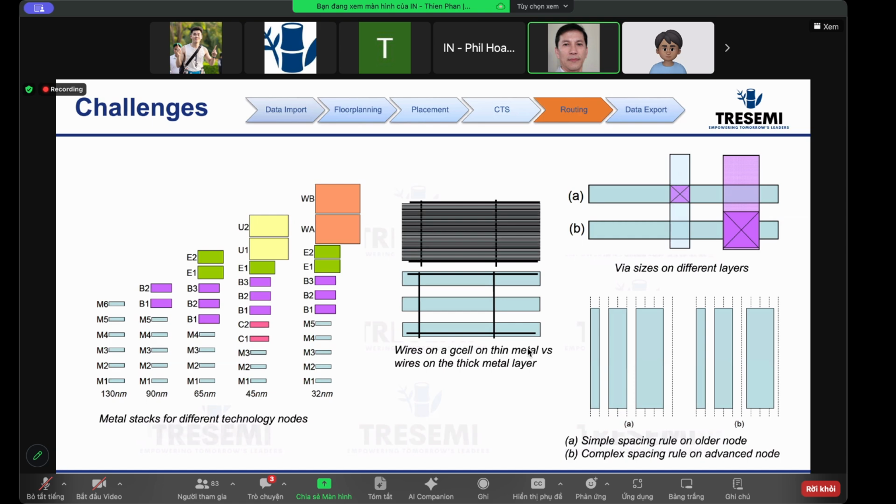And also when the wire is so small, during manufacturing when they're etching, they can over-etch the wires. So what happened is there's no longer a single pattern. They do what's called double patterning, which is two patterns for one wire so that it can maintain the shapes.